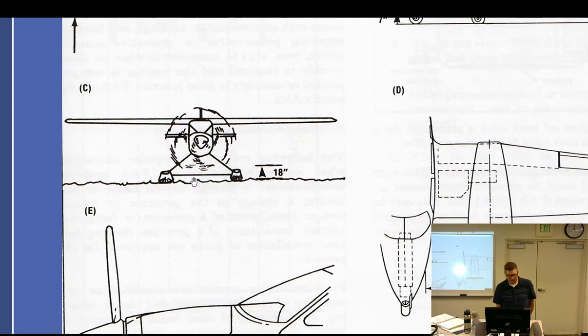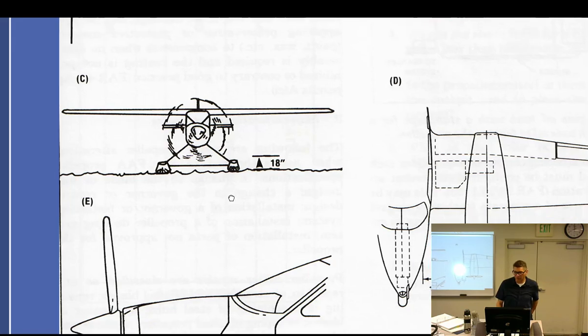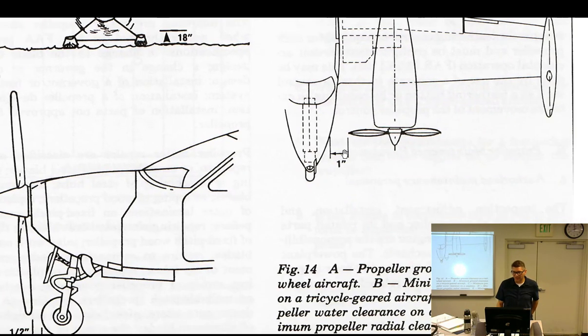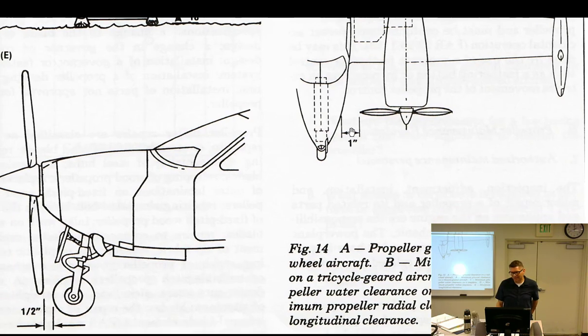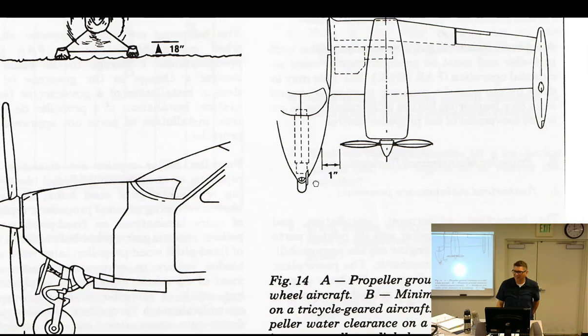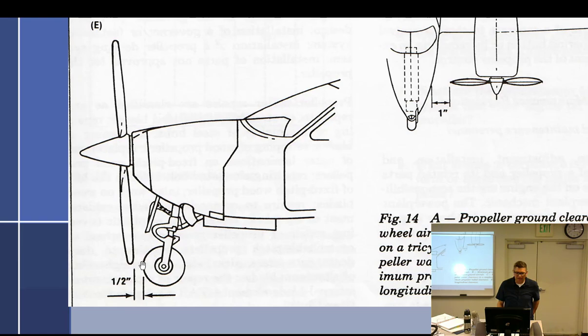18 inches on the water, because water does a lot of damage to props. A lot. I told you about rain. As long as you've got a good inch there, it probably won't hit it. Watch out for the stretch. And half an inch from other components.